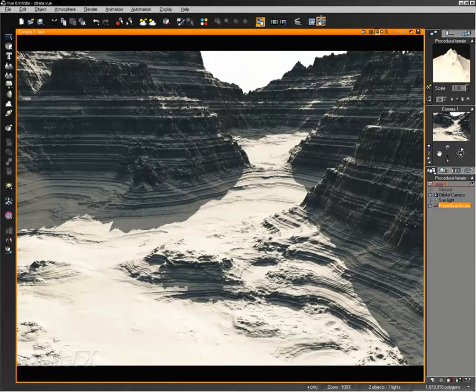So with this being stretched out so much on the Z, we're seeing a lot of artifacts around the areas where it's such a harsh cutoff. And that's because the terrain is being pulled upward from a flattened set of geometry. So anytime you have a really steep slope on any terrain, it's going to have a little bit of tearing.